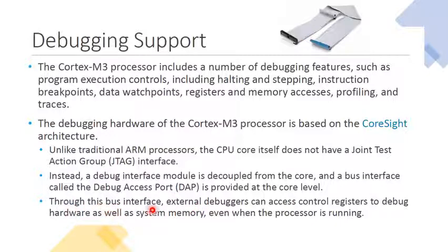Through this bus interface, external debugger can access control register to debug hardware as well as system memory, even when the processor is running. So I hope this example is clear to you. We shall come back to these points one by one.